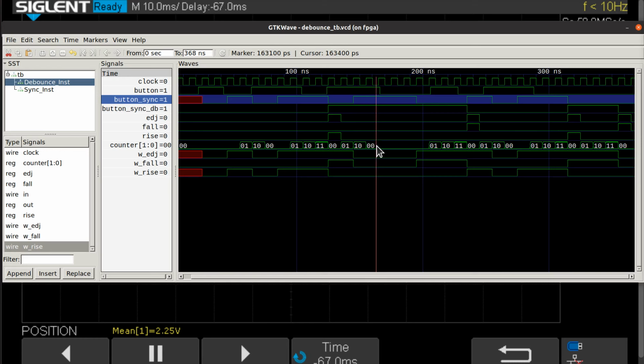Counter goes back to 0, and it wants to wait until it gets all the way up to 3 here, while the input is 0. It's not till over here that the input's low long enough for it to be recognized as being acceptable. And then you see the output go 1 to 0 there, a single tick cycle that says it just went low here, and so on.